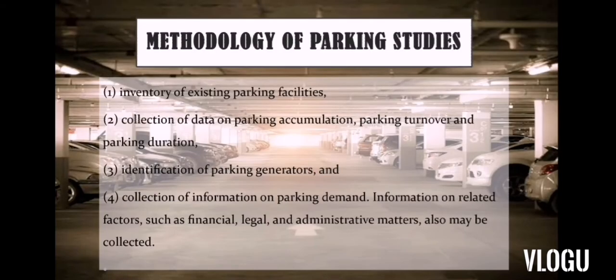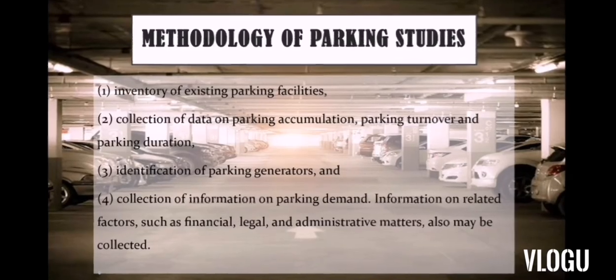Methodology of parking studies. A comprehensive parking study usually involves, first, inventory of existing parking facilities, second, collection of data on parking accumulation, parking turnover, and parking duration, third, identification of parking generators, and fourth, collection of information on parking demand. Information on related factors such as financial, legal, and administrative matters also may be collected.